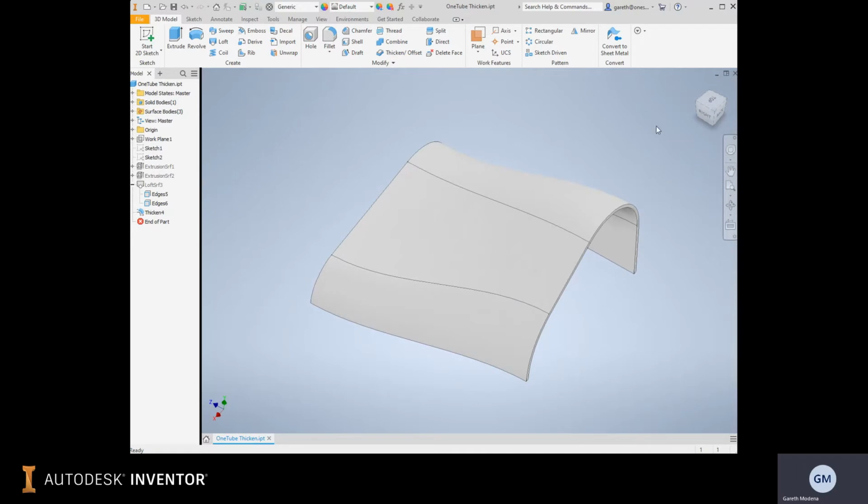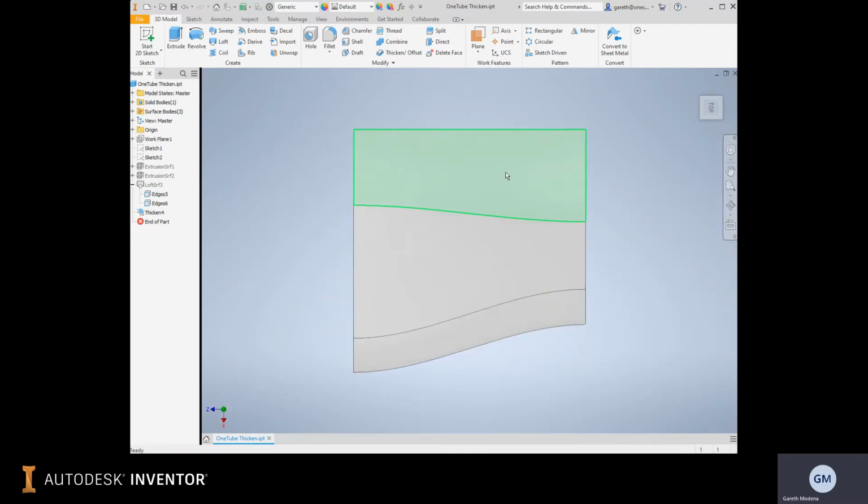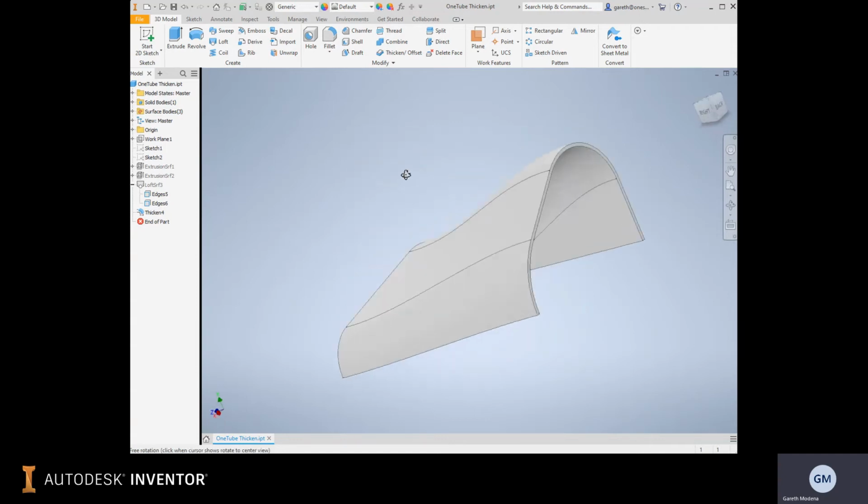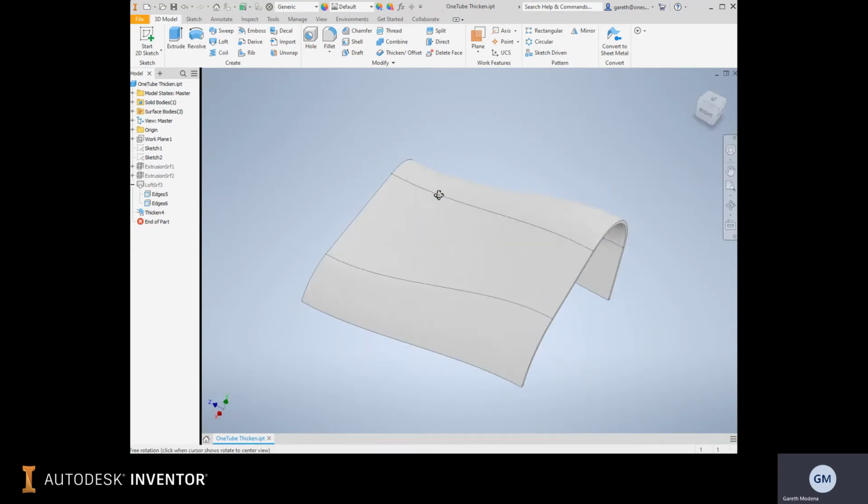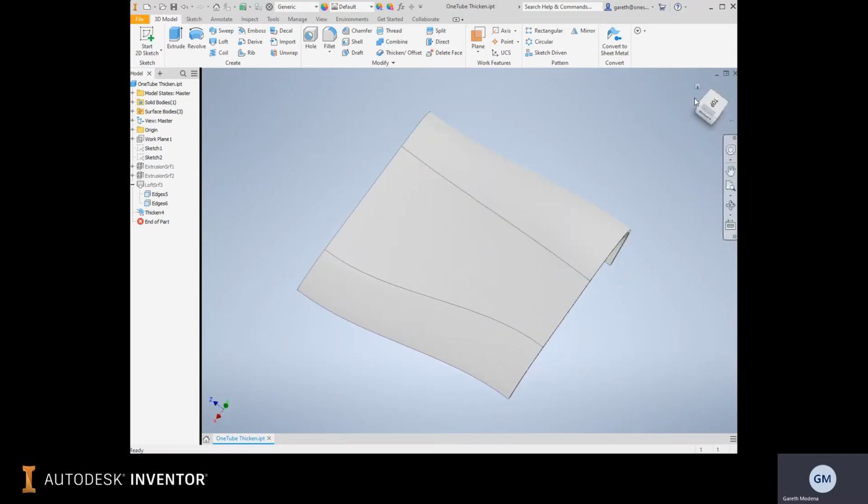So in this example, we want to create a cutout that needs to represent an elliptical hole that needs to cut this body. So you could have just used a normal extrude and cut that out. That is the alternative. I just want to show you how to use the split tool in order to be able to create that representation. The split tool can be used for other scenarios as well.